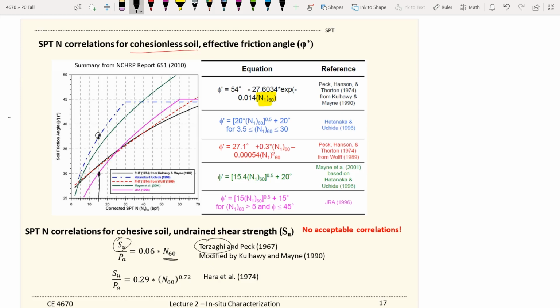It's a very simple correlation. But he put a note in his publications saying that you need to use those correlations with caution, especially for clay materials, because it's not reliable for correlating SPT with clay strength, because too much disturbance is caused by using the SPT. So we end up with the SPT correlations not being very reliable.